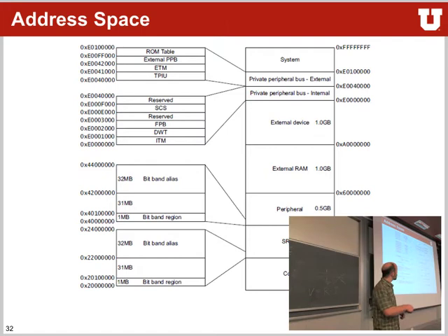So what you can see is we have something that's called the code space. We have something that's usually the RAM space, where you have RAM memory. You have the peripherals that are sitting somewhere in the memory, and we will look into that later on when we talk about memory mapped I/O. You can have external memory that you can talk to, more external memory, private peripheral buses, more private peripheral buses for external off-chip system things, and a system memory map. We will look into several of these different things later on in the lecture.